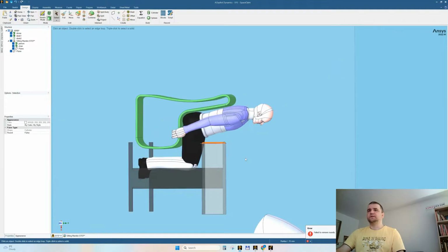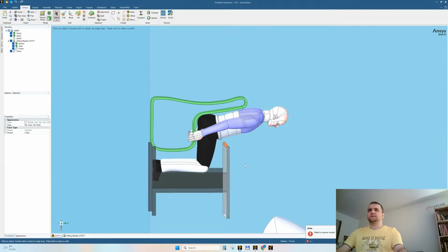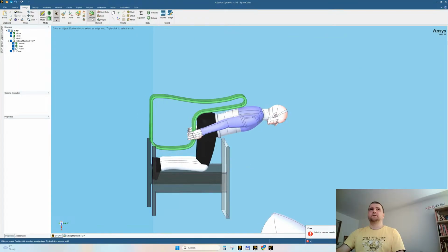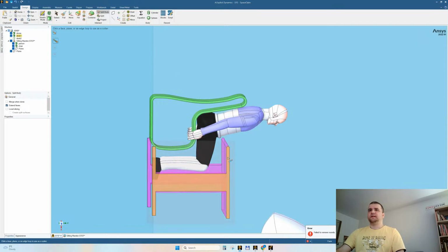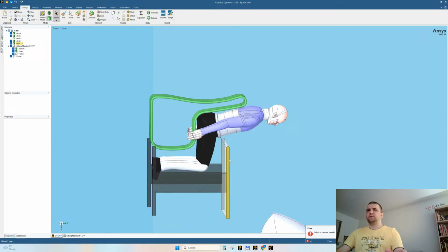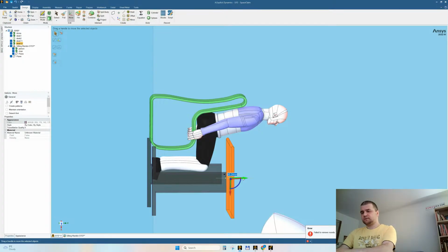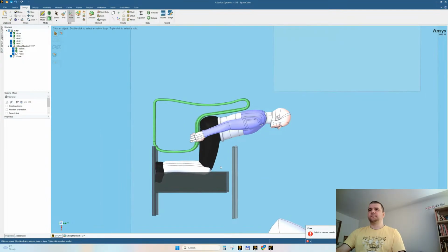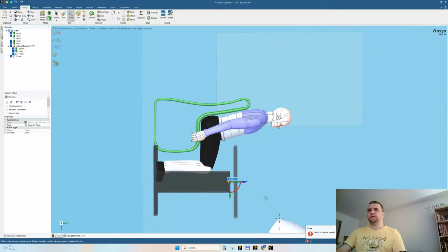Can I delete this now? Is it possible? Is it or not? Split body. I will split the desk with this face, and now I will bring this inset more to the right. 55, let's say, all right? And now these faces, I will pull up to U from the keyboard.